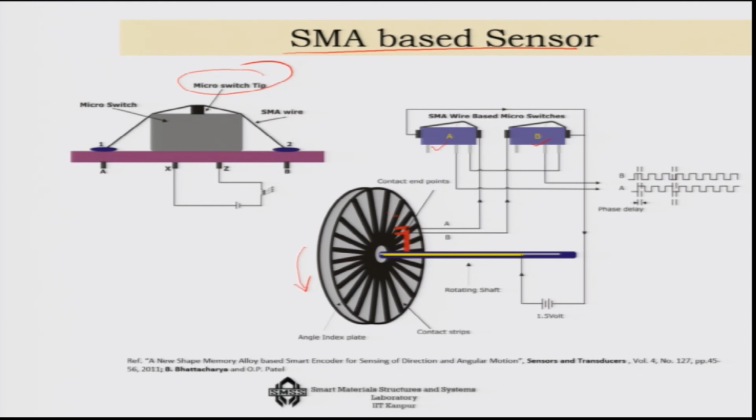Whenever they are at the 2 conductive strips, there will be current flowing, and as the current flows, you will get heating here, and this switch that we have here will be pressed. So, that means the current will be flowing on. The next moment, if one of them goes here, that means the current is not there, so it will once again lift up. So, you will be able to see this kind of current flowing, no current, current flowing, no current situation.